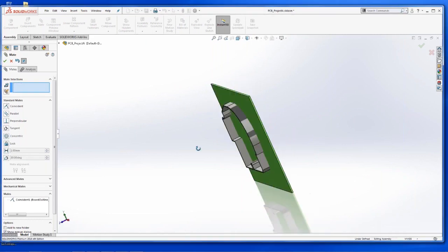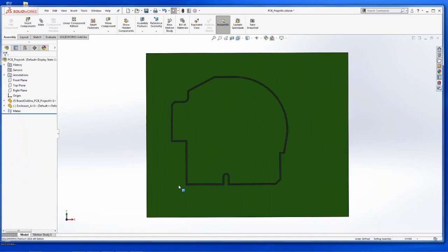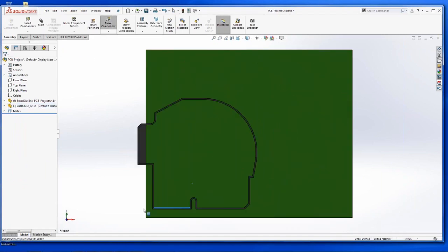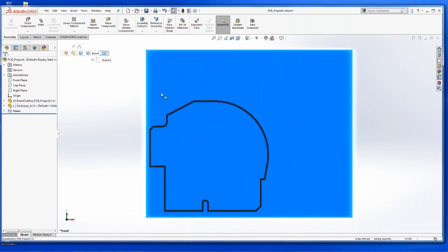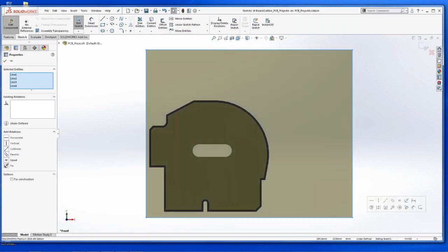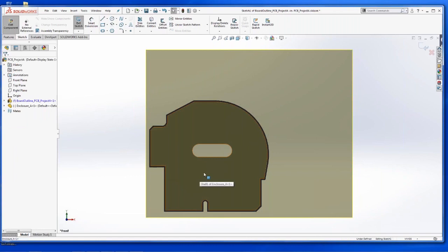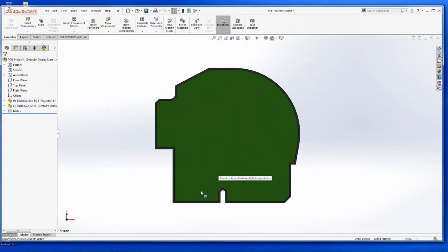Okay. Now we're able to slide, obviously, the chassis anywhere we like on the surface of the PCB, and we won't lose that reference, right? So by dropping that down, we're good. Now we just simply need to edit the board sketch. Okay. We can delete the perimeter because we're going to use this inside surface, and we're going to make that the board. All right. So now in 2 clicks, we've got a board with slots.